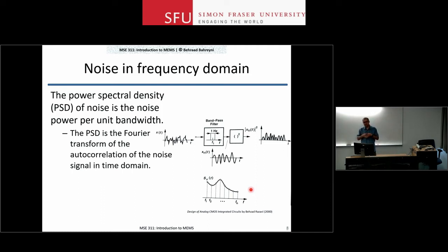And if you think about the frequency representation of an impulse, we saw from the Fourier transform courses that you took before that an impulse has a white spectrum, meaning that it has all frequency components in it. So each one of those impulses produces all of those frequencies if they're fast enough, and that's the noise representation in frequency. So how do we characterize it? How do we quantify it? What we say is, let's measure the noise power in a limited bandwidth. Well, let's define that limited bandwidth to be 1 hertz.